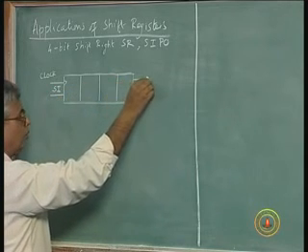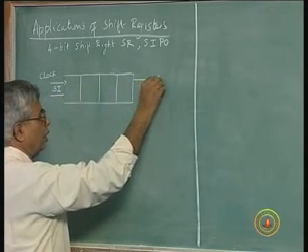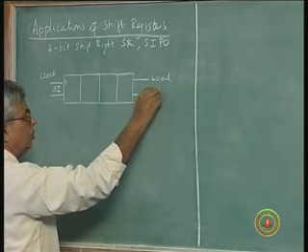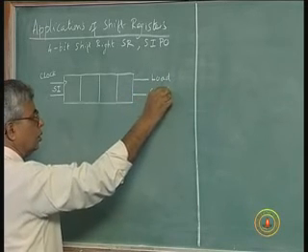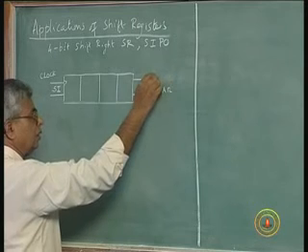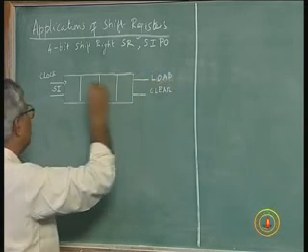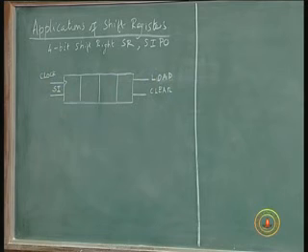We should also have load and clear features, because you want to start with a pattern. That you can do by putting the data in one bit at a time and shifting it. That's one way of loading. The other way of loading is to give parallel inputs and then give all the bits at the same time.